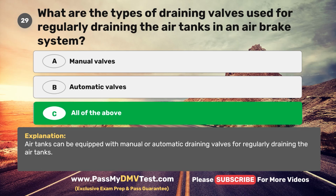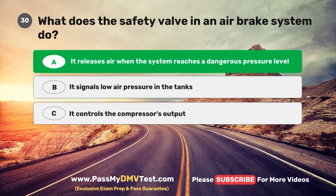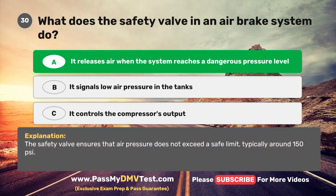Question 30. What does the safety valve in an air brake system do? A. It releases air when the system reaches a dangerous pressure level. B. It signals low air pressure in the tanks. C. It controls the compressor's output. The correct answer is A. It releases air when the system reaches a dangerous pressure level. The safety valve ensures that air pressure does not exceed a safe limit, typically around 150 psi.